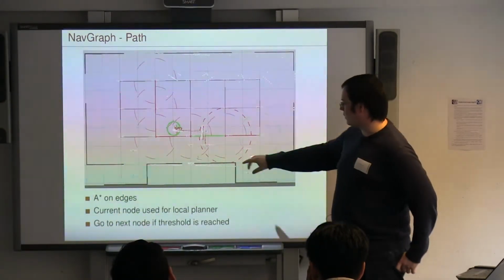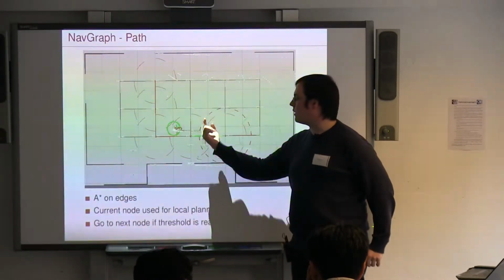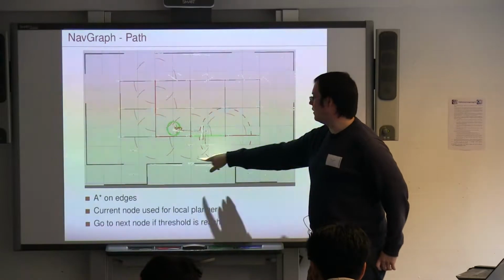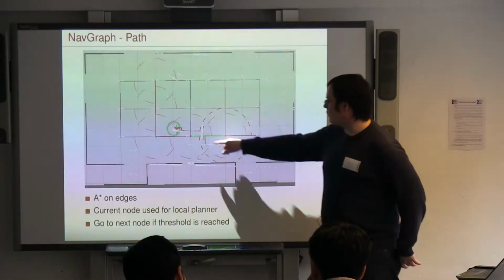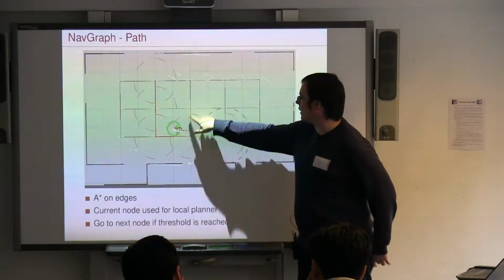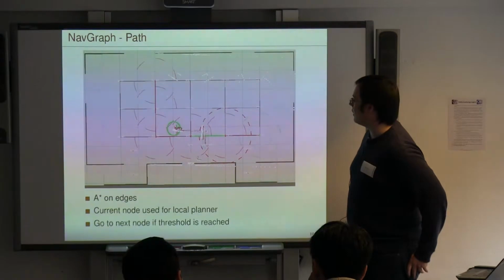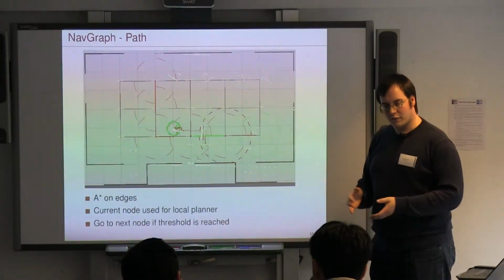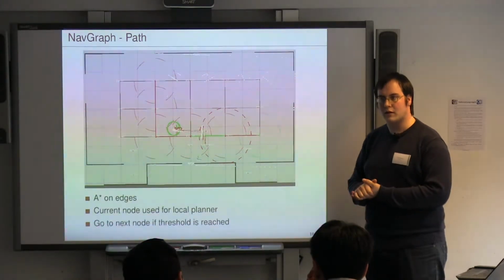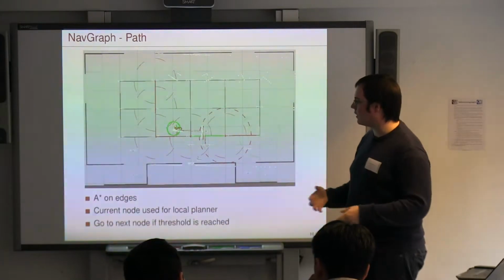These zones are always 1.5 meters in the Y direction and 2 meters in the X direction. So this is always one zone where an MPS can stand anywhere inside. And we use this as a good first idea where it's unlikely that an MPS is standing, so it's unlikely that we have an obstacle in between.